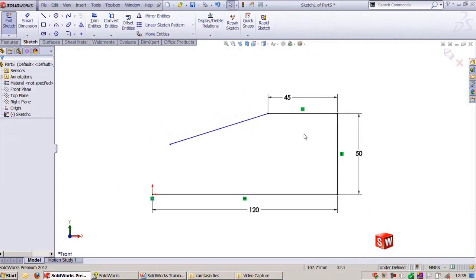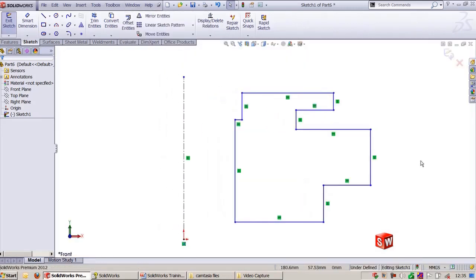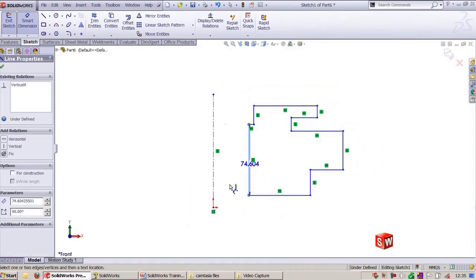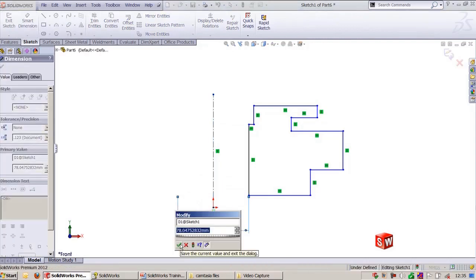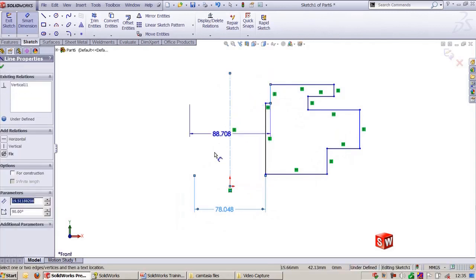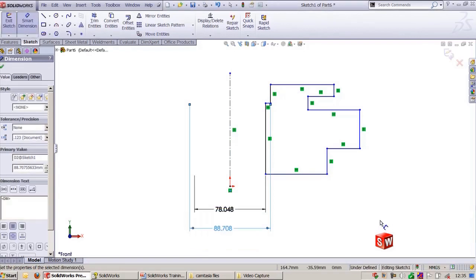The next one is doubled distance, which is one more interesting relation in SolidWorks. When you go and detail any revolve section, we will create a diameter dimension representing it in this way. How? Go to dimension, select this line segment and the center axis, and if I drive this, you will get this doubled distance we normally use for cylindrical geometries, and this we call doubled distance.